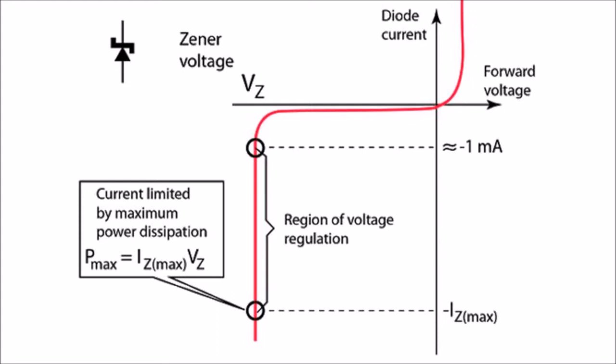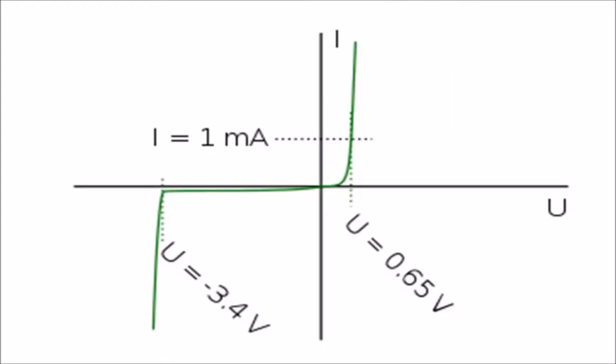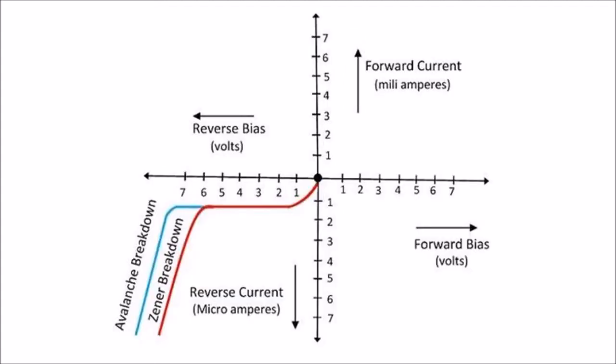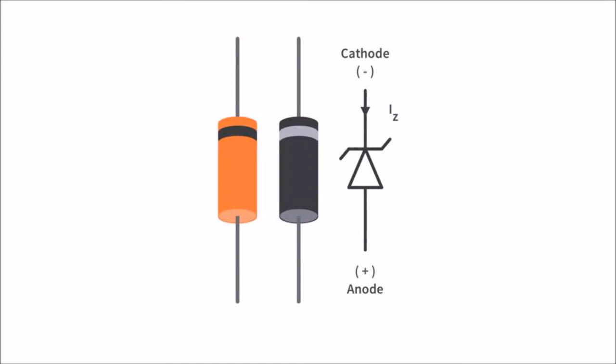Diodes with a higher Zener voltage have a more gradual junction, and their mode of operation also involves avalanche breakdown. Both breakdown types are present in Zener diode, with Zener effect predominating at lower voltages and avalanche breakdown at higher voltages. The Zener diodes are widely used in electronic equipments of all kinds and are one of the basic building